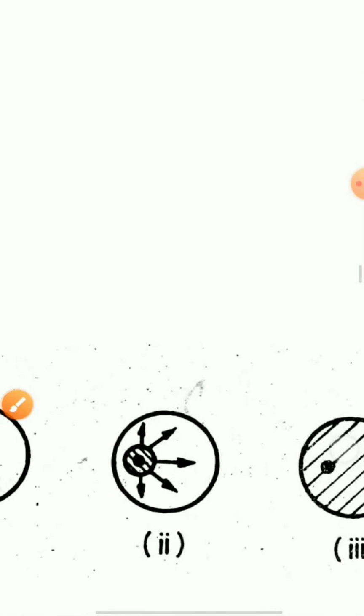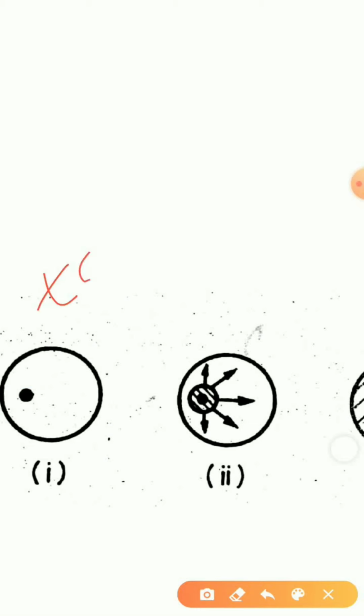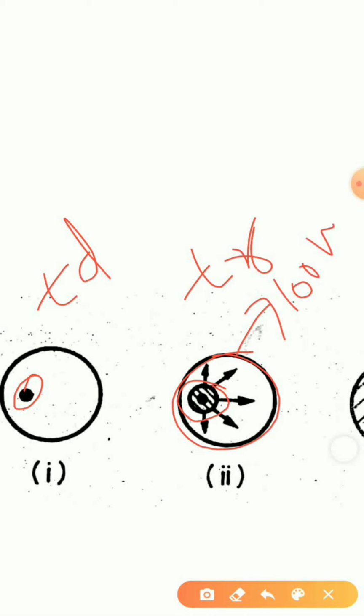Hotspots means, initially during delay time, current was flowing only from a small region. During rise time, the current flow is trying to establish itself, so some current is trying to flow from a larger area. Now for the entire area, if I had 100 watts of power flowing, and for this small area I am having 100 watts of power flowing, where will the temperature rise be more? The temperature rise will be more in the second case. Now this is what is happening here.